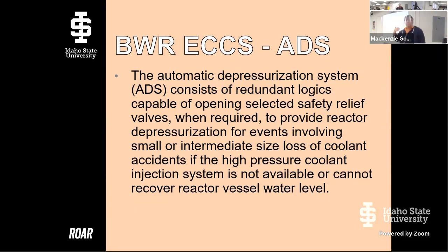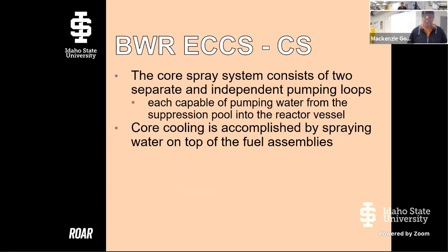So you have a small break, you have your high pressure injection system, but for some reason, you couldn't get your high pressure injection system to work, but you still need to deal with this emergency core cooling. So let's very, very quickly depressurize the system so one of our low pressure systems can work, right? And so this removes the need essentially for them to have that intermediate one as they just deal with the pressure, okay?